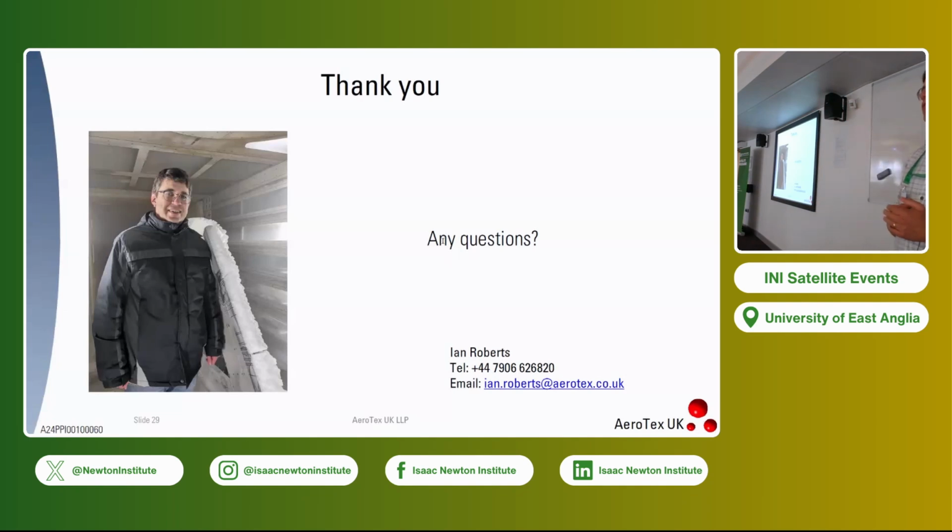Yes, there's quite a lot of work being done at the moment to look at ice-phobic materials, so looking at designed surfaces. It's going to stick, it's just to make it low adhesion. But the problem is they tend to be soft surfaces, and we've tested about 20 and none of them have survived. They have to go into a rain erosion rig, which I think is 3 millimetre droplets at 300 metres per second, and after about 10 minutes they're not there anymore.